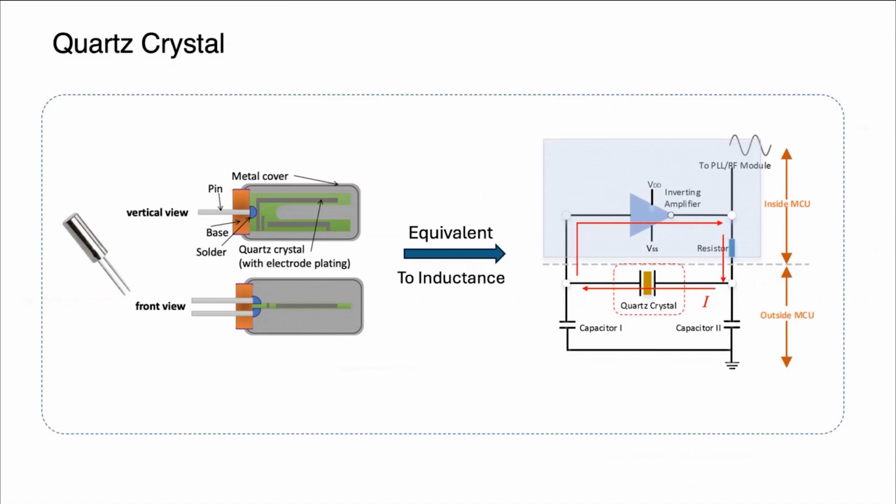The crystal oscillator is a core component of RTC circuits. An RTC uses a tuning fork-shaped crystal oscillator to generate the oscillation signal, as shown on the left side. It is equipped with a crystal with a resonance frequency of 32.768 kHz, covered in a metal can, and plated electrodes are attached on both sides of the crystal surface.